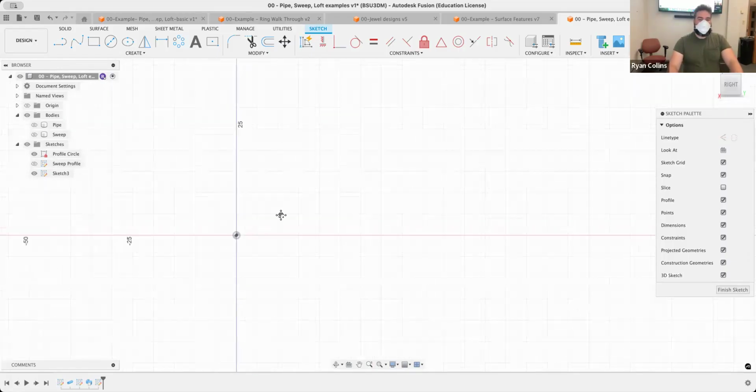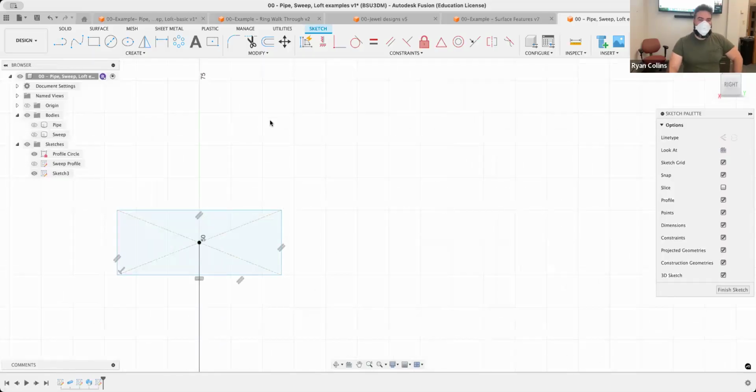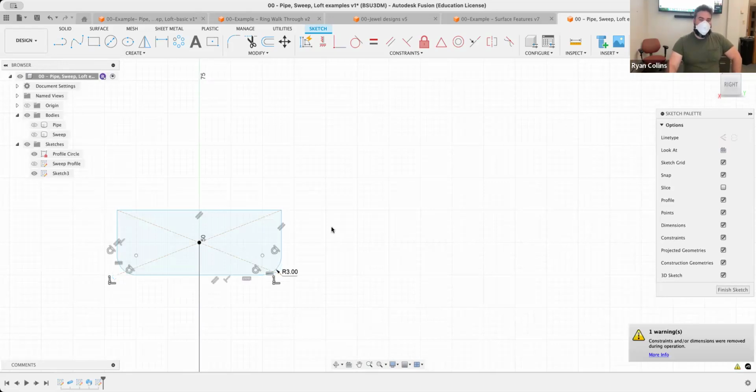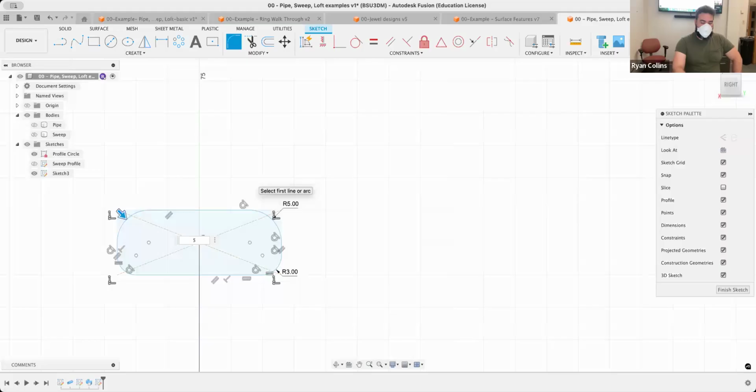I'm going to go back up just because I feel like it. I'm going to put a fillet on, let's see here. Let me round out the bottom. Remember, you can put multiple fillets around a rectangle if you don't press enter. See, it's saying 2. All right, bottom to side on that one. Now I can alter that, and it changes both of them together. All right, do that. Right click to bring up the same tool. I'm going to alter the top one differently. All right. And now instead of 2, I don't know, 5 more. I could drag this too. Only so far though.